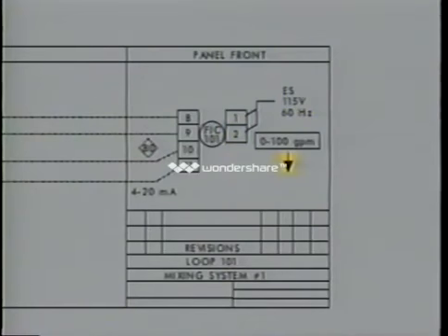The arrow pointing down lets you know that this controller is reverse acting. The diamond symbol shows a set point of 80 gallons per minute. Its operating range is 0 to 100 gallons per minute. The signal line from the controller takes the signal back through the junction boxes to the field process area.